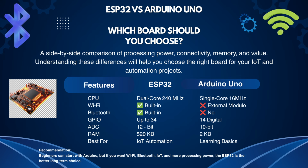When it comes to connectivity, the ESP32 has built-in Wi-Fi and Bluetooth, allowing it to connect directly to wireless networks and smart devices. In contrast, the Arduino Uno requires additional external modules for Wi-Fi and does not include built-in Bluetooth. The ESP32 also offers up to 34 general-purpose input and output pins, giving you greater flexibility when connecting sensors, displays, relays, motors, and other peripherals.